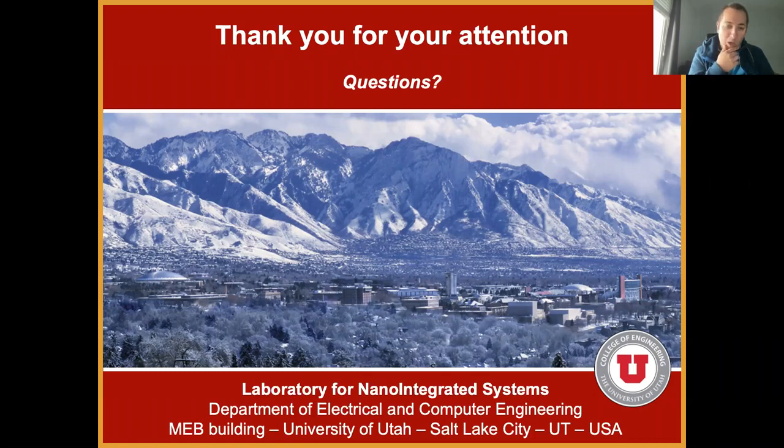in a better way. We had a paper a couple of years ago where we said, let's do an MIG-based optimization. Let's look for the critical paths and map those critical paths on the adder blocks in an FPGA, called the carry chain, basically. So we use the fast carry chain to implement the critical path. There's a lot of potential in that.